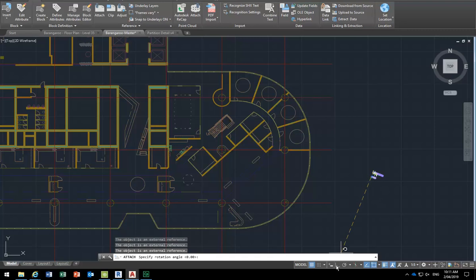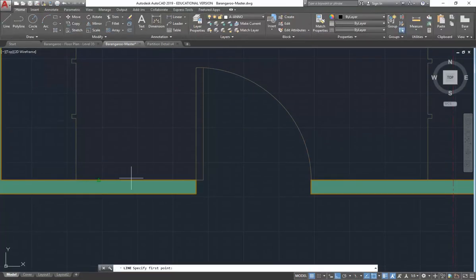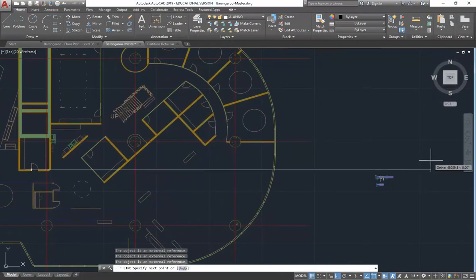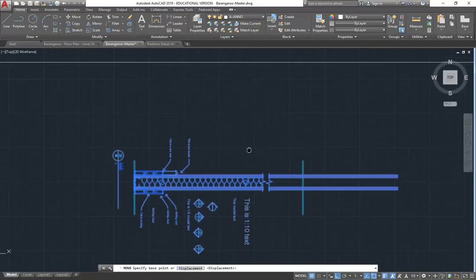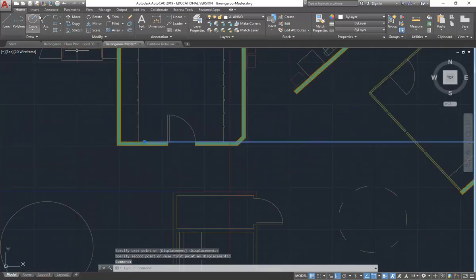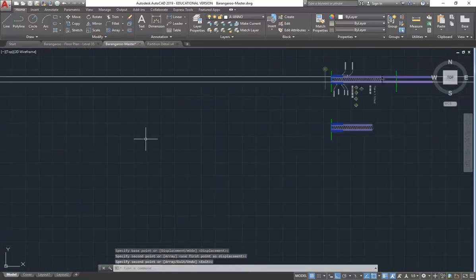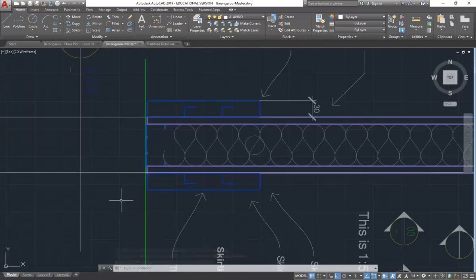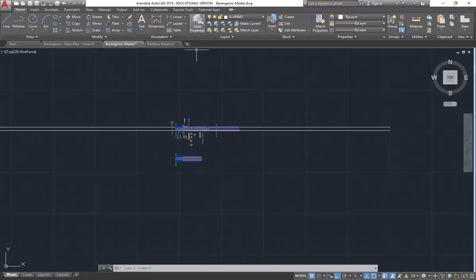And then I'm going to turn on ortho just so I can rotate that 90 degrees. Okay, and so then we could potentially have maybe this wall that we want to be taking that detail from. So then I can project lines from there and take them across to line them up with my partition. So I'll move that now to line up exactly with that line, and then potentially we can have that line coming down, and hopefully that's got the right width. Yeah, pretty close. That's right, so we can fix that on the page.